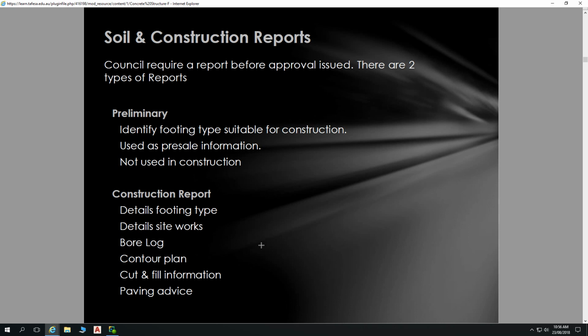So with adding moisture to soil, you know, through landscaping, through sprinklers, through moisture recharge wells, which are little things that sit in the ground and distribute moisture. I've drawn up several jobs for moisture recharge wells to ensure that buildings' footings are not being stressed during summertime. So the construction report wants to also mention these type of things.